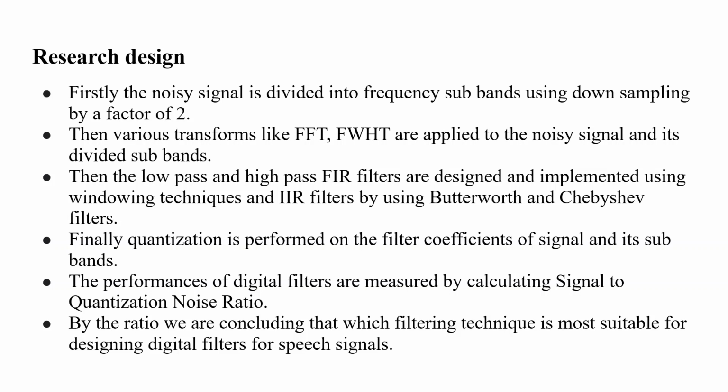Then the low pass and high pass FIR filters are designed and implemented using windowing techniques, and also IIR filters are designed and implemented using Butterworth and Chebyshev filters. Finally, the quantization is performed on the filter coefficients of the signals and its subbands.